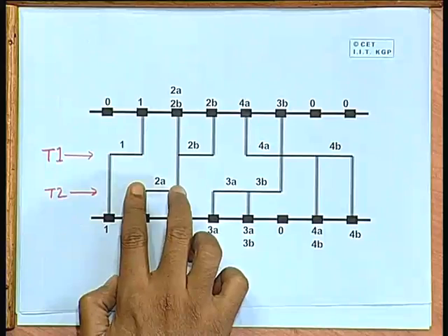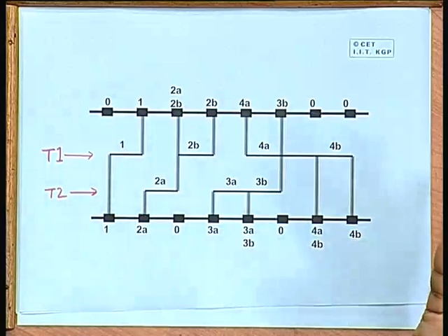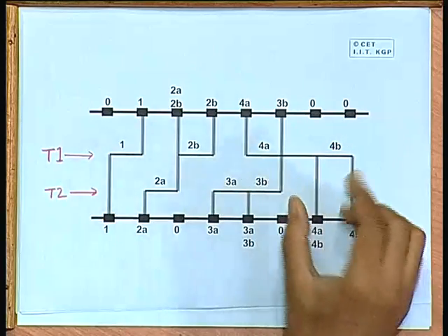But the problem in this method is that, well, if you have many nets with multi-terminal pins, then the number of nets you have to consider in the modified problem goes up quite considerably. The number of these split nets become pretty high, because ultimately we are applying the left edge algorithm, the number of nets you have to consider there will be large. So, there is another algorithm which we will be presenting now, that gives a good solution, but that does not consider dogleg. Without dogleg, that gives you a fairly good solution.